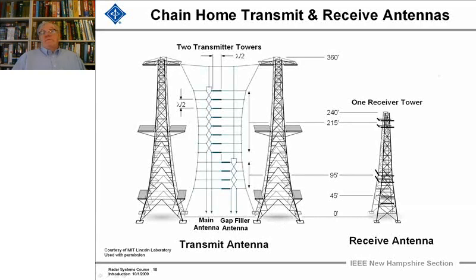And one of the receive towers, here's just one of them we've visualized here, they were wooden and 240 feet tall. They would receive the signal with a cross dipole at 95 feet and 240 feet, and look at the phase difference of the signal in altitude with one set of receive antennas.